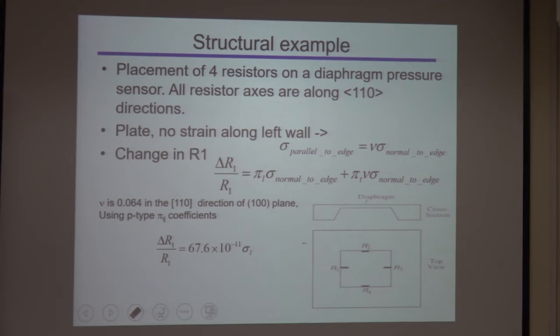But for a paper like this one, if I put a large force, it cannot support it and will just deform. So for a very thin diaphragm, there is almost no stress in the Z direction, and we can forget about Z direction stress.